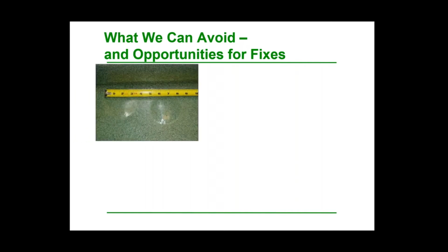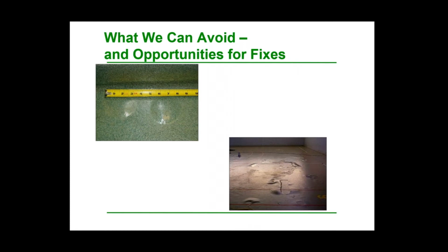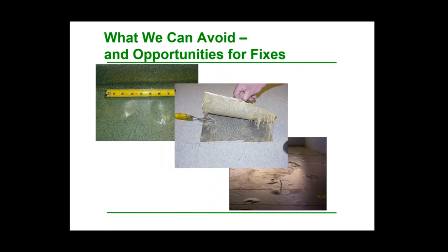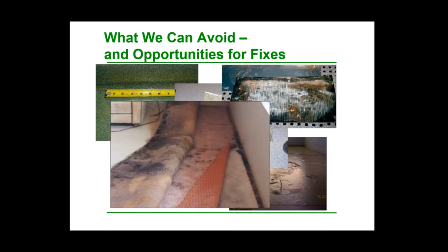Obviously, this picture here is of a resinous floor with osmotic blistering, which is caused by high levels of moisture in the concrete. Here, more widespread blistering and debonding of a sports flooring system due to high moisture. Here we have a picture of emulsification of glue, normally caused by high pH or very high moisture conditions, but primarily the high pH, as well as floors like these, which have tile and carpet with mold. Mold seems to be affecting these systems because of the high exposure to all of that moisture, high relative humidity, and moisture vapor emission.